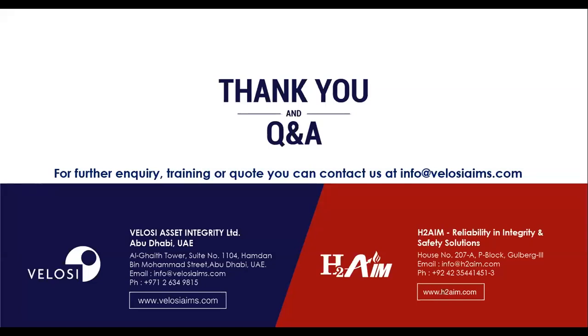Okay, next question. As per NFPA, foam is a suitable medium for extinguishing chemical fire, UN class 3, but we see water sprinkler systems in chemical storage warehouses. Which standard is considered to have a water sprinkler system in a chemical warehouse? See, it's a very serious issue. The compatibility of the water sprinkler system or water spray with the chemical has to be studied.